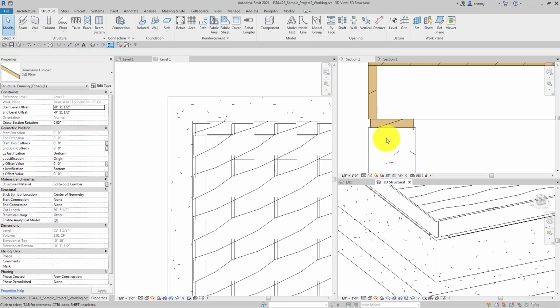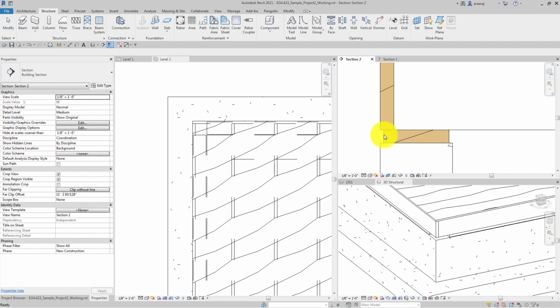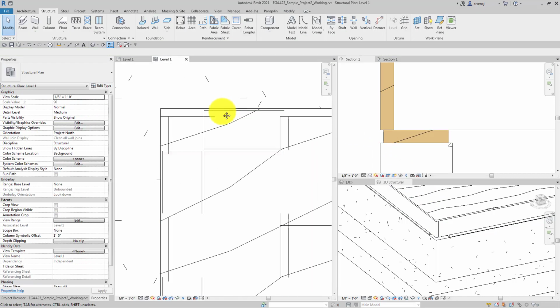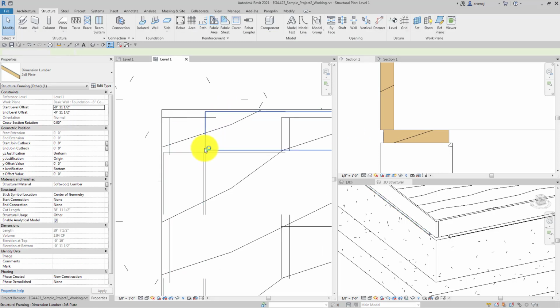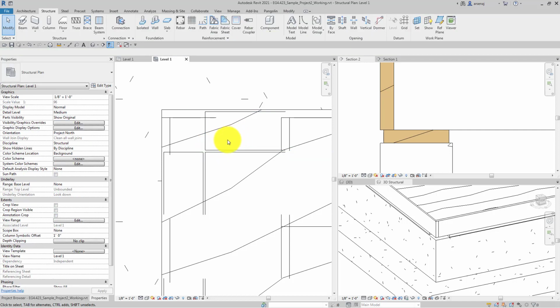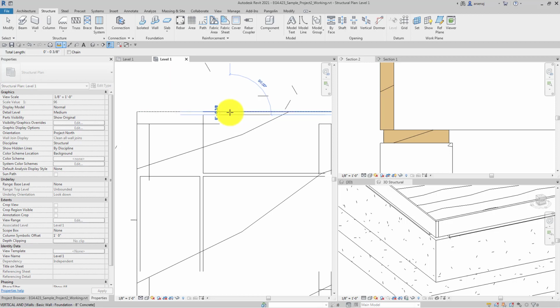Put it at the top of this wall in the correct orientation, and it looks like the offset, just like we were looking at some of the other placements, is a little off. Also, I noticed it didn't connect like the other ones did. It looks like they're not connected, but that's okay, we can fix that. So the first thing let's do is get this offset so that we have it at the face.